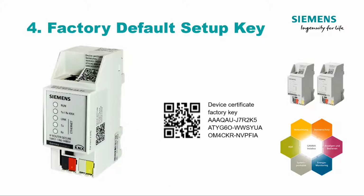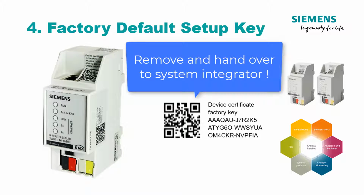Factory Default Setup Key, FDSK. The so-called Factory Default Setup Key is required for safe commissioning. The Siemens KNX IP Secure products have attached this key to the housing in the form of 3 QR codes. One of these labels should be removed before or at the latest during installation and handed over to the system integrator who creates the ETS project.